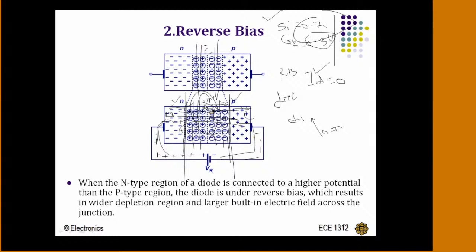Now, you will get full clarity on this concept with the help of a whiteboard, because here I am not able to clearly draw the picture or annotate perfectly. The simple conclusion is: in the reverse bias, there is no diffusion current because opposite polarities were connected to the N-type and P-type material. The width of the depletion region is large, so majority charge carriers cannot diffuse from N-type to P-type or P-type to N-type.